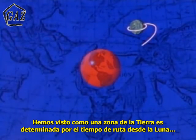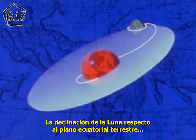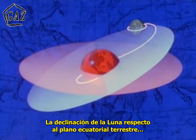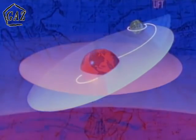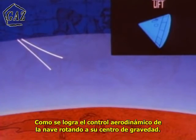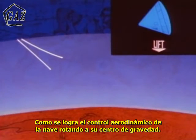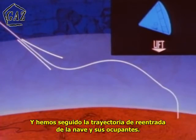We have seen how the landing area on Earth is determined by the time of travel from the Moon, the declination of the Moon relative to the Earth's equatorial plane, and the plane of the trans-Earth trajectory. We have seen how the entry corridor is defined, how aerodynamic control of the command module is achieved by rolling it about its offset center of gravity, and we have followed the spacecraft and crew through the entry trajectory.